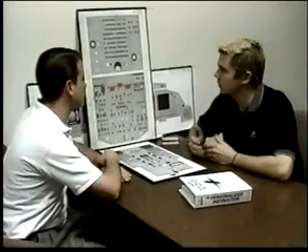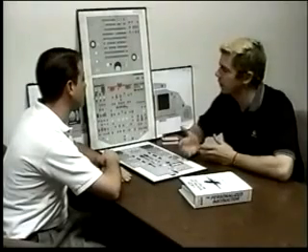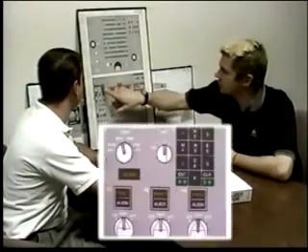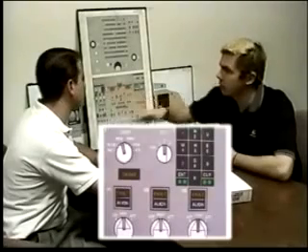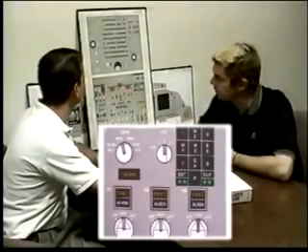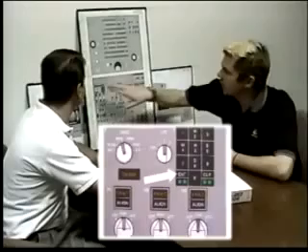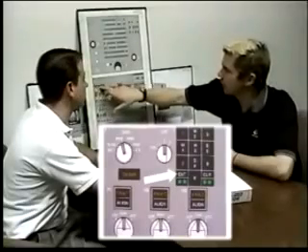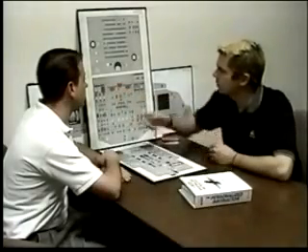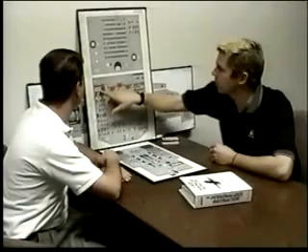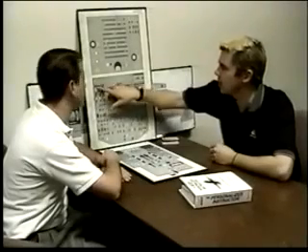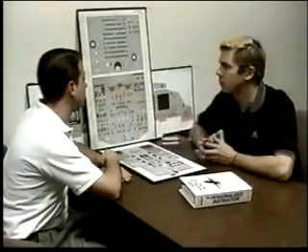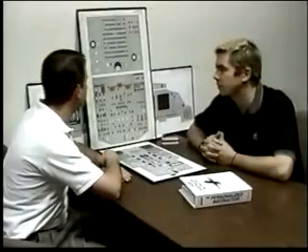For instance, if I looked on the whiskey compass and I saw we were doing 265 degrees, I would enter 265 and then 0 for 0 tenths. I can't read a tenth on that. And then I'd hit enter. That's going to come up here and give me my magnetic heading up there. You've got to realize though that if I look for number 3 or number 2, it's going to tell me a true heading as opposed to a magnetic heading that I'm entering.